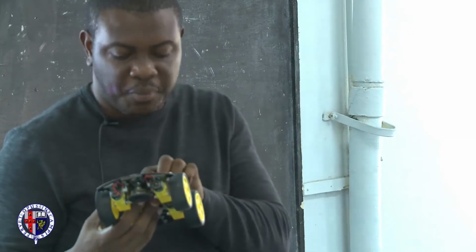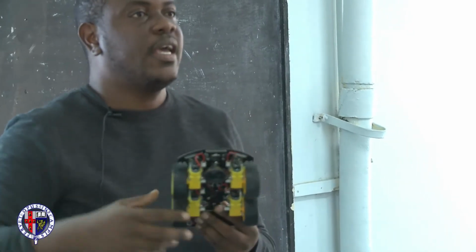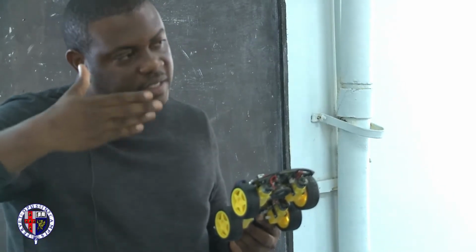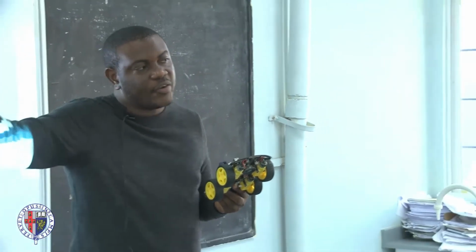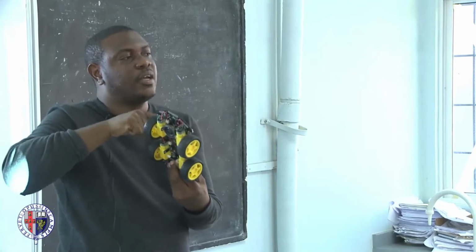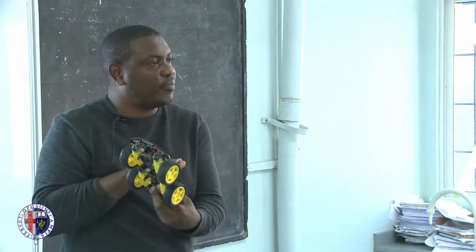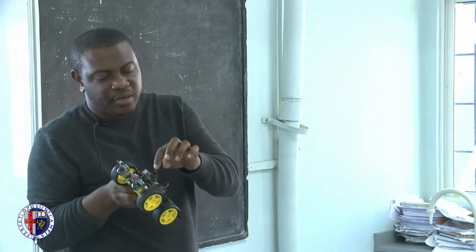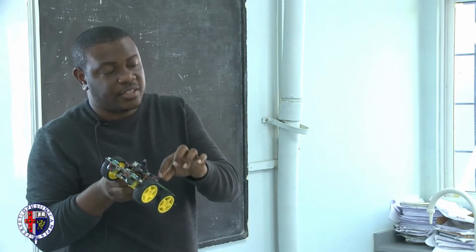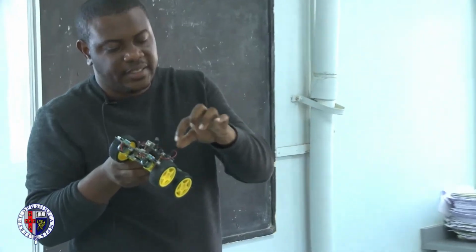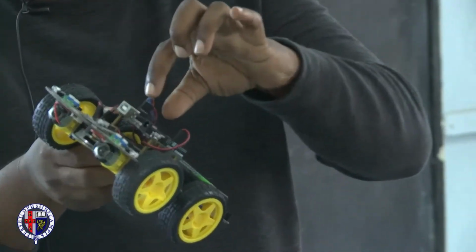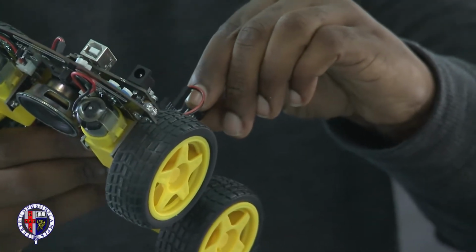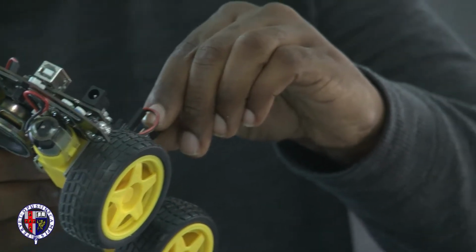These pulse width modulation pins allow you to send different voltage values to the motors. And of course, as the voltage values increase, the speed increases. But only these pins over here could do that. These ones could not perform pulse width modulation. So no problem. The brown wire can just fit one way over here. I have 6 of these, and there are 6 slots. So it's just a matter of moving from here to here for me to get that constant speed.